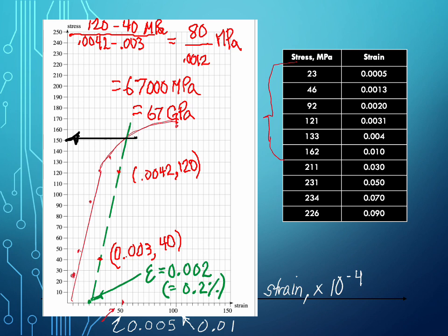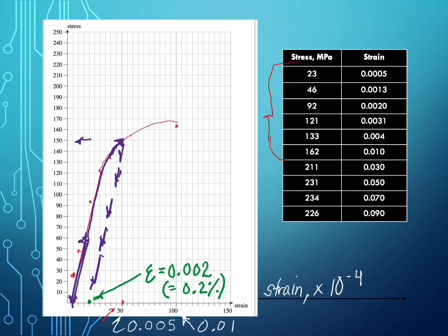Now, I want to just try and help explain the name of the yield strength, the 0.002 yield strength. On this next slide, we talked at some point about the fact that here we are in the linear region, and any place in here, if I load within the linear region and then unload, I'll have zero permanent deformation.